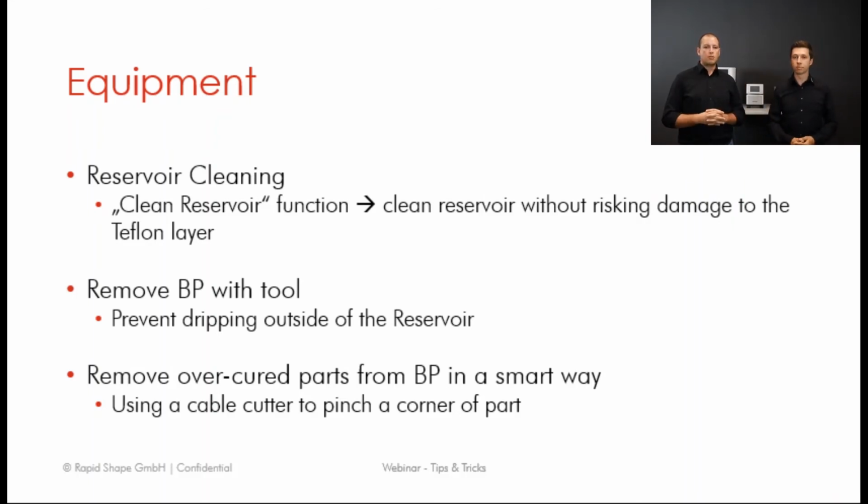So it might not be apparent, but like Robin said, the bottom limit switch is at a length such that if the build platform is not inserted, it doesn't crash into the reservoir. If you crash the load cell into the reservoir, you are creating less of a moment because of the distance at which the contact is being made, and then ultimately you can A, break the reservoir, B, damage your load cell, or C, even worse, break the liquid of the reservoir.